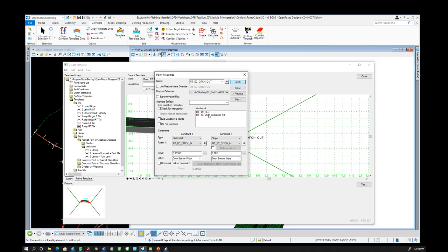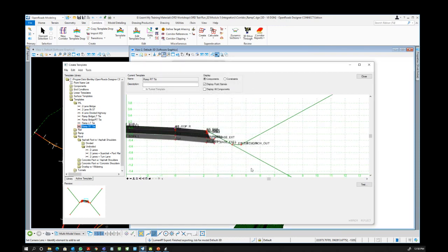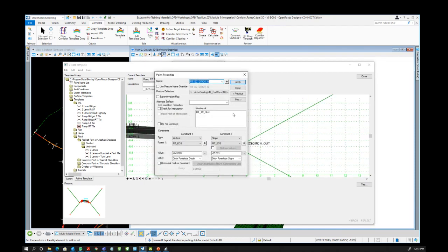If you're talking about the corridor itself, yes, you can. You just need to customize your end condition points. You see here, 1:4. You can change this value to 33% or whatever is needed. It's bounded by the boundary condition. Then it targets your existing ground, basically. It terminates at your existing ground.